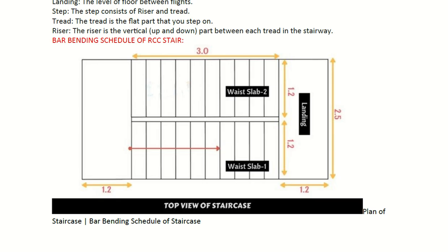Okay. This is the straight length, but your base slab is not straight. So 3 meters like this. Okay, but the base slab is like this. So the first thing you need to do is calculate this length. How do I calculate this length? Pythagoras theorem, right? So in this case it will be the square root of 3 square plus what?